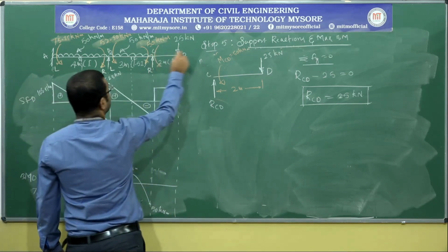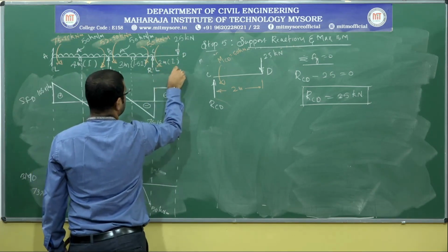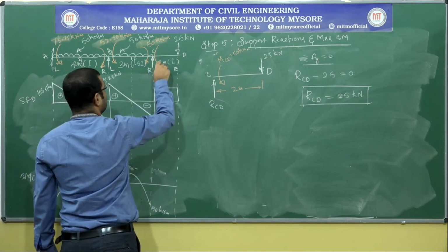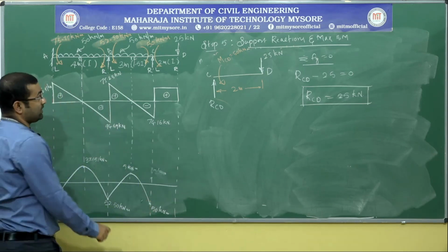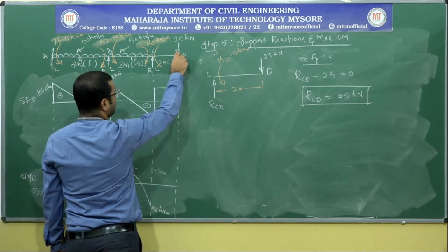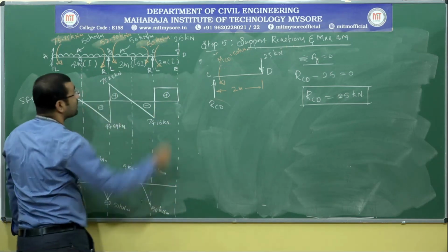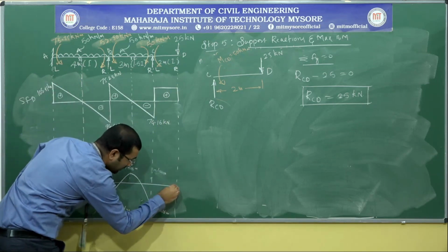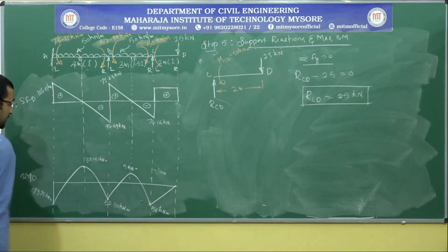And if I consider this for bending moment, C will be on the left side and D on the right side. Left side we have an anticlockwise moment, it means it is negative, which I have marked. Right side MDC is 0. So this is a point. Because of the point load, the variation in the bending moment diagram is linear, right.